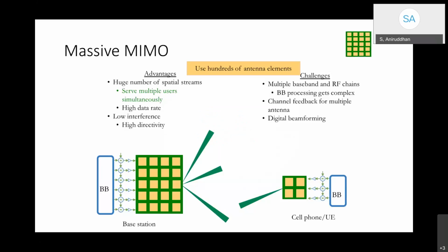Streams to do what is called beamforming. I will talk a little more about beamforming in the next slide, where it will become a little easier to understand. But the basic idea is, in this massive MIMO system in the sub 6 gigahertz range, the beamforming is done digitally, where you can tune the antenna to direct the antenna to look in a particular direction to receive a signal, or transmit the signal in a very